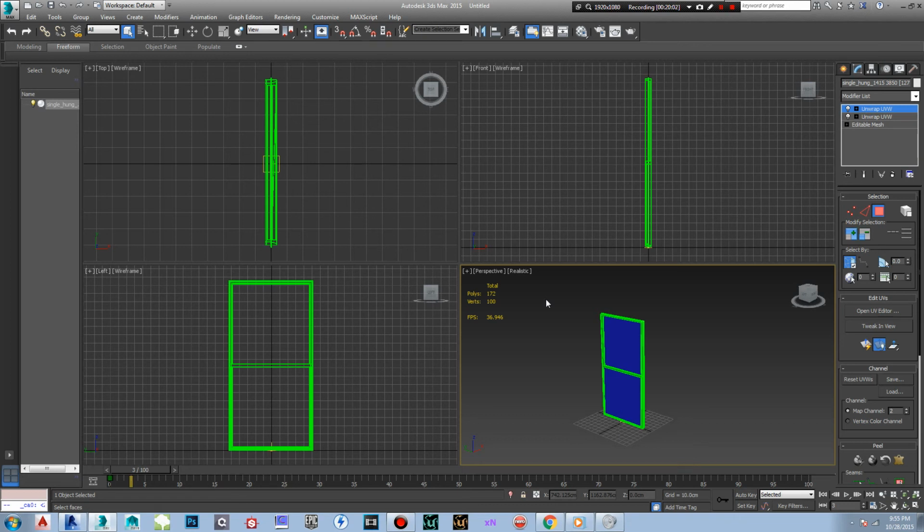It will ask you if you want to keep the unit, the FBX file settings, which will be saving your other 3ds Max file or Maya file settings, or if you want to bump up the unit scale to what you have at home. You want to bump up the unit scale, so you want to scale it up to the customized settings in 3ds Max. You'll see when you see the pop-up menu if you've ever done it before. So okay, that's out of the way.